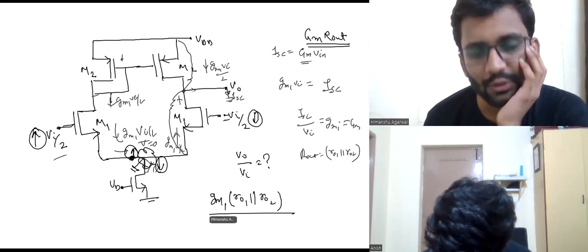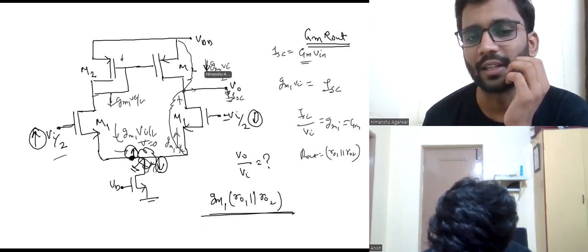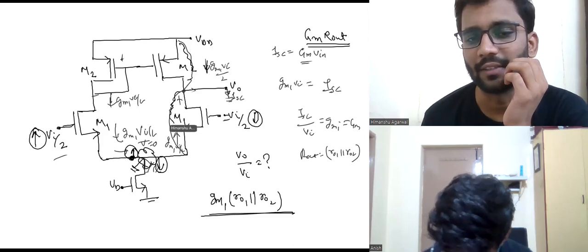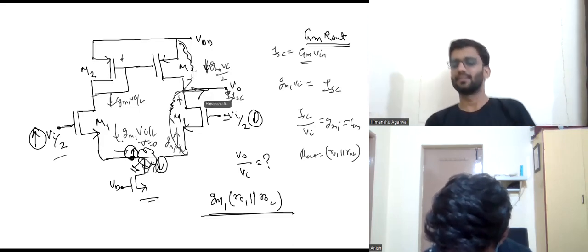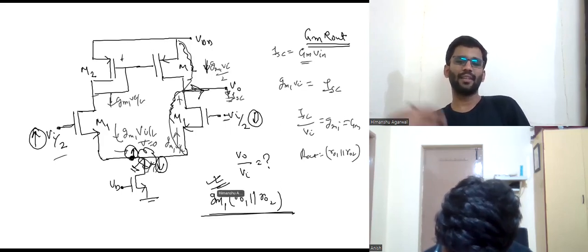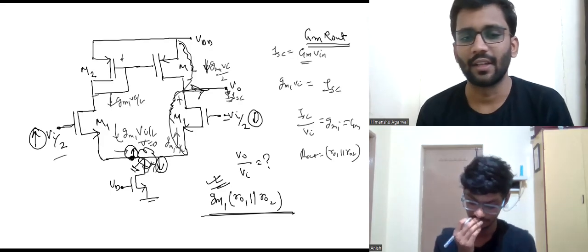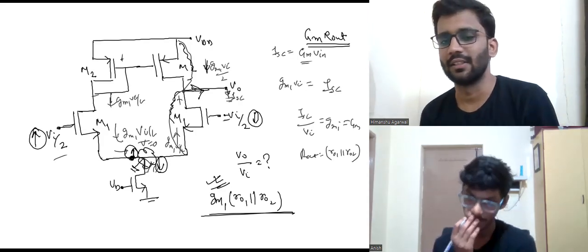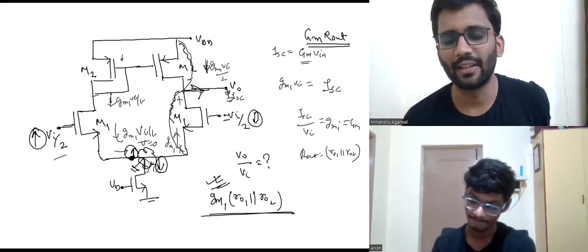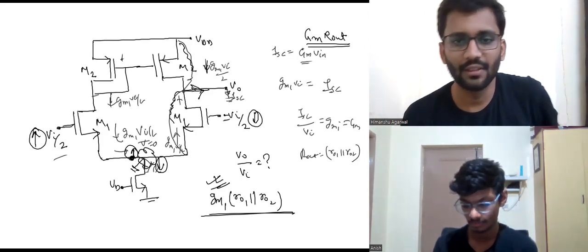So you made an assumption here when you were writing the current, that these are very high, so the current would not go into these two. Yes, that was an approximation. It would otherwise be a bit difficult. From that we can make the single stage op-amp. That's just a common source amplifier we will make here, and we will get the op-amp. That's the basic idea.